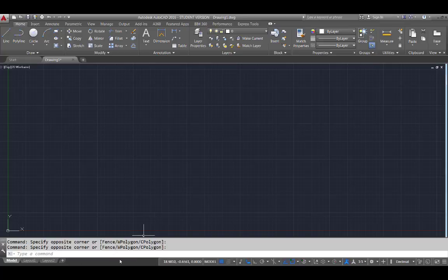The other thing at the bottom, finally, once we leave the drawing screen, below the drawing screen is something called the status bar. Status bar has some tabs over here on the left. Model, layout 1, layout 2. Every AutoCAD drawing has 1 model space and 1 paper space, but paper space can have multiple layouts in it. So you'll always see 1 model tab, but you may see many different layout tabs. And that's what you're seeing on a typical AutoCAD drawing that we opened up here.